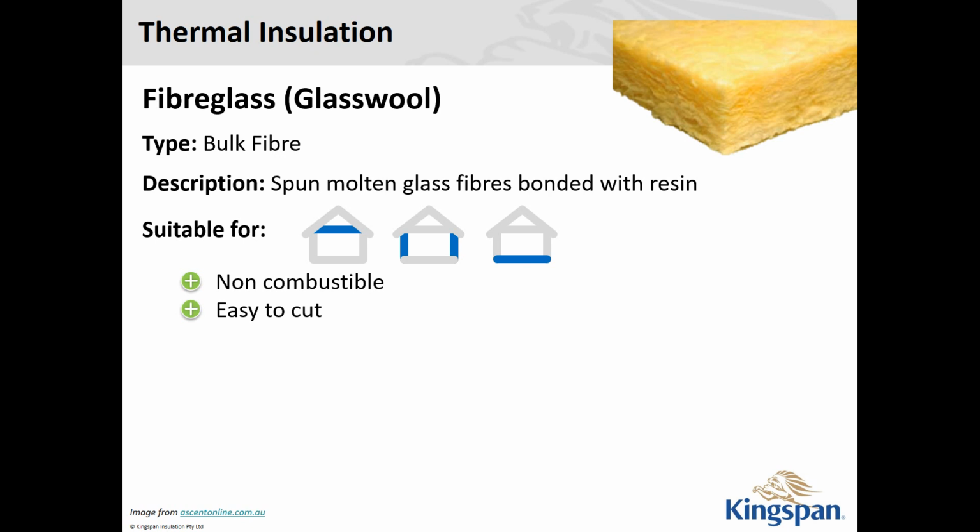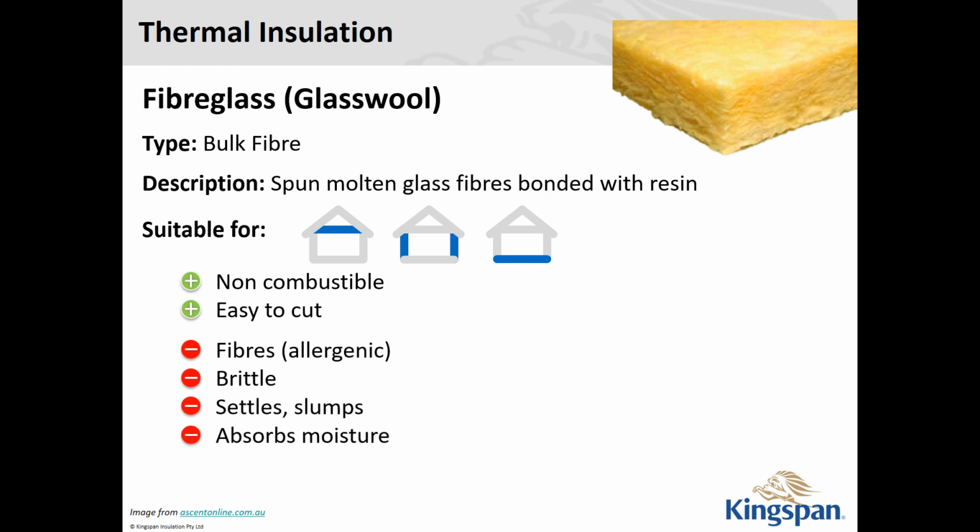That's correct. We get phone calls a lot of times where people have allergies and that type of thing, so they're looking for alternatives to insulate their buildings without anything that has fibres associated with it. But I think one of the major limitations is the style of roof you're doing. If you're doing skillion roofs or a raked ceiling where you don't have a great deal of depth in your ceiling, sometimes there's just not the space to achieve the required R values with the bulk insulation.